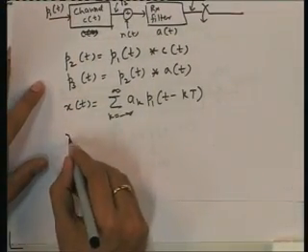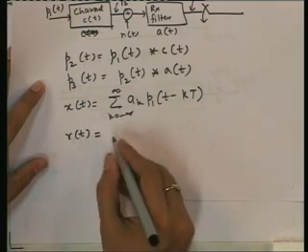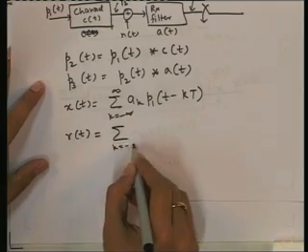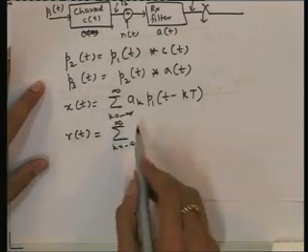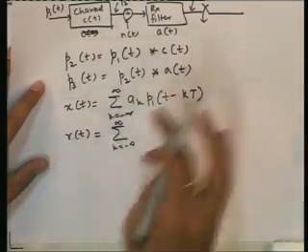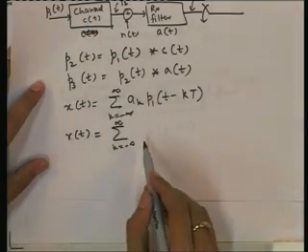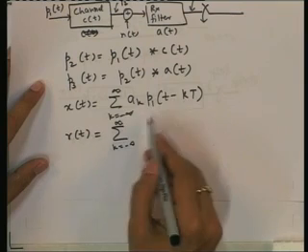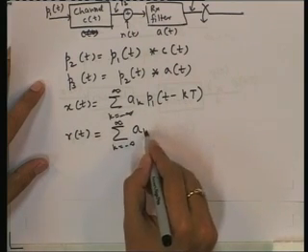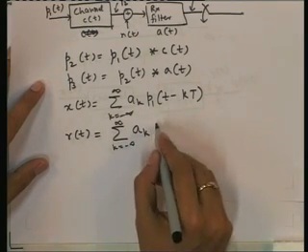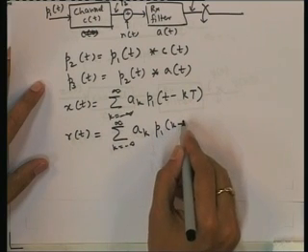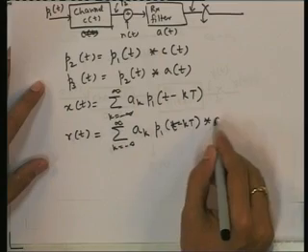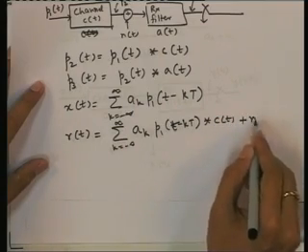We receive r(t) equal to the summation, k equal to minus infinity to infinity, of this whole thing convolved with c(t), it is going through the channel, plus noise. So the convolution can be taken inside the summation. So we can write a_k, then p1(t minus kT) convolved with c(t), plus n(t).